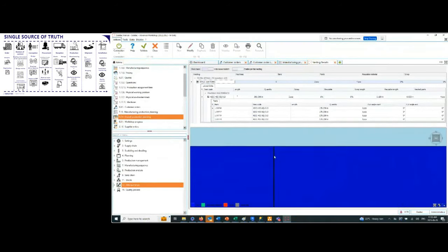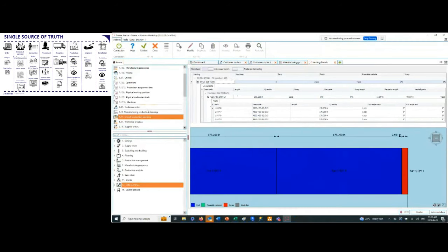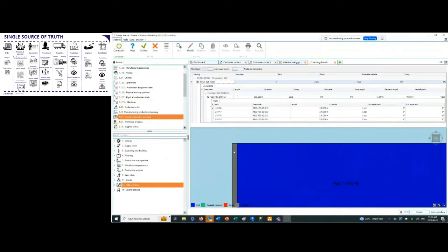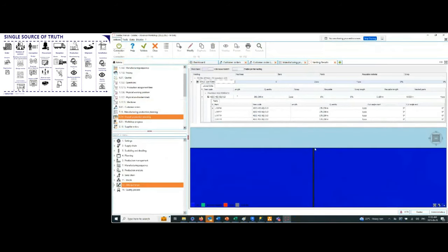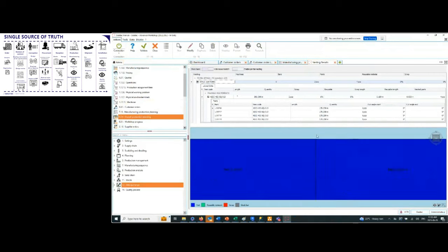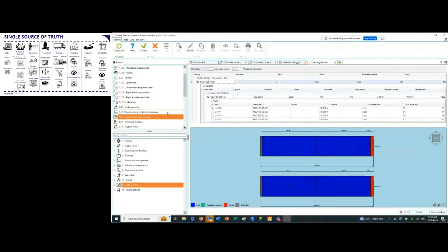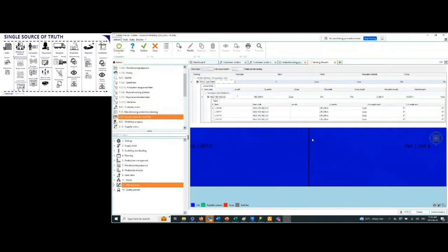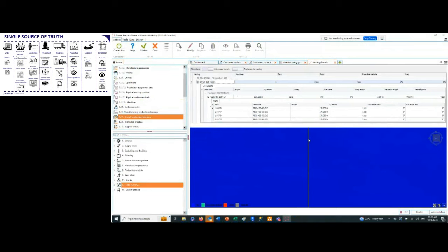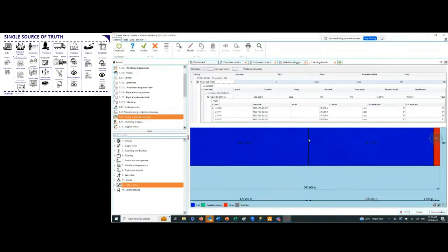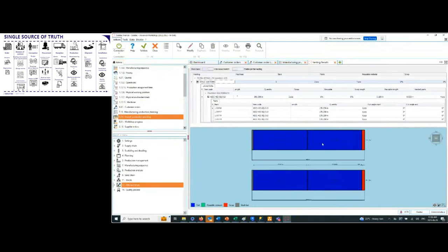And also here, there are other factors that you can alter and change with the machine configuration. So of course, when we tailor the workstations and machines, we factor in the initial cut variables with the machine parameters. And also the blade width thickness, if it's dealing with a saw, or how much material would be removed when cutting a bar element into 2. So those are factors that you can manage within the machine's configuration. And if you want, you can be more conservative with your blade thickness. Okay, you can put an actual value and an economic value.